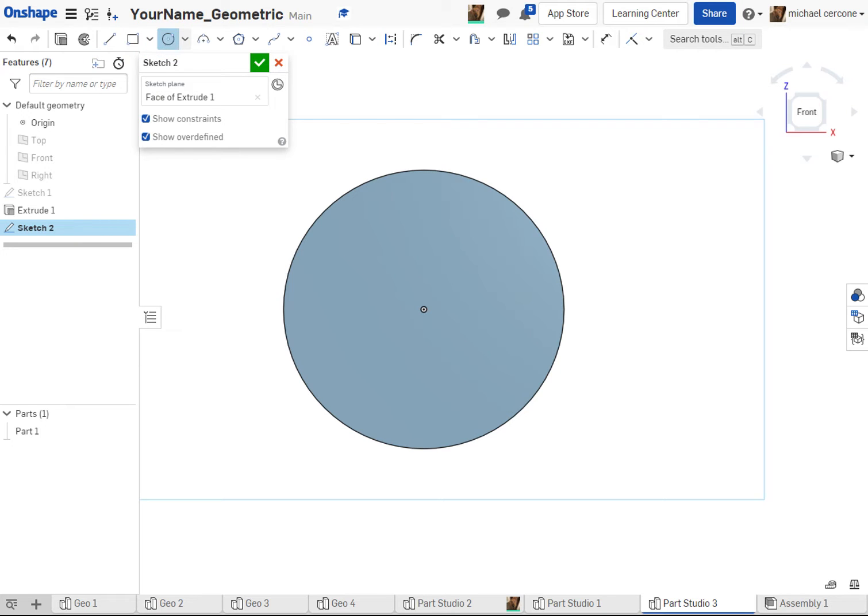So I'm going to start with 2 construction circles. The first one figures out where the 1/2 inch radius is at the top. And this one is a 3 5/8 diameter, so 3 plus 5 divided by 8. The one at the bottom, it's very difficult to tell, but it is in line with the 3/4 radius on the second slot that we'll be designing. So this is a 3/4 radius or a 1 1/2 diameter.